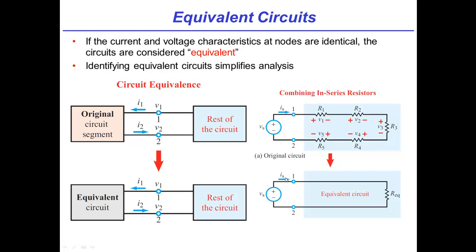I see. So we know that the equivalent resistance, and we'll go into this in more detail later, of those 5 resistors is R1 plus R2 plus R3 plus R4 plus R5. And what you're saying is, we know this because if we replace those 5 resistors with this one resistor, that's the sum of them, for a given voltage source Vs, we'll get the same current. So effectively both of these circuits look the same to the voltage source. That's right. If I'm a voltage source, they make me produce the same current for the voltage I'm applying. That's a really nice, succinct way of putting this.